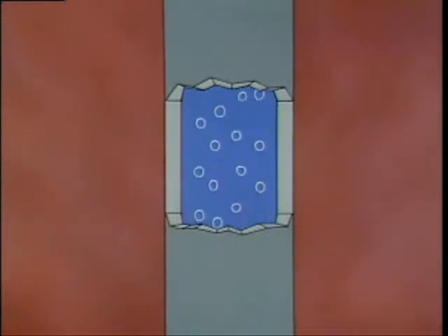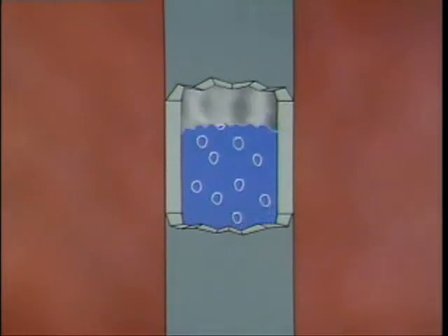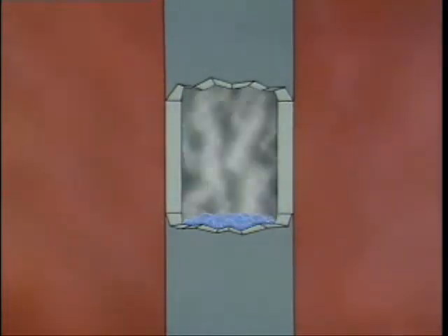A heat transfer problem can also occur if the feed water supply stops for any reason. Without a continuous supply of feed water, the boiler may boil dry. With no water to remove the heat, the tube metal rapidly overheats and severe damage may result.